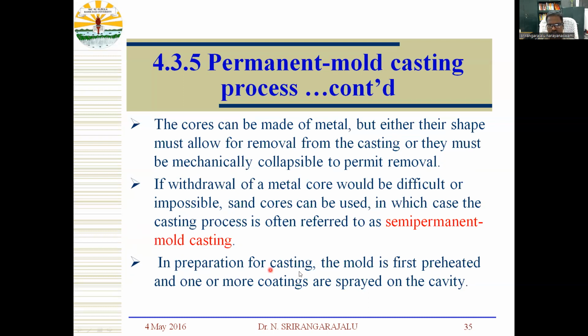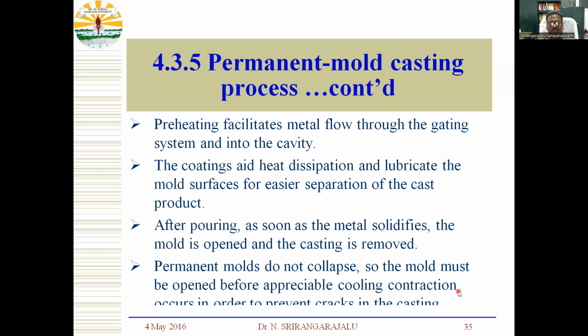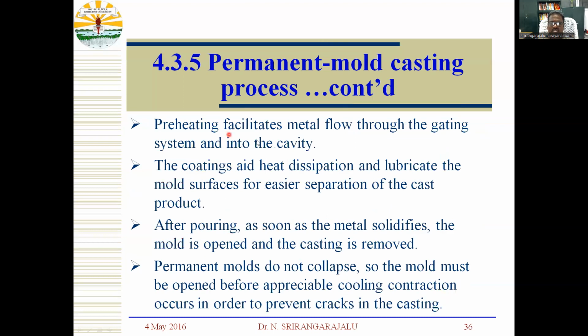In preparation for casting, the mold is first preheated and one or more coatings are sprayed on the cavity. Preheating facilitates metal flow through the gating system and into the cavity. The coatings aid heat dissipation and lubricate the mold surfaces for easier separation of the cast product.